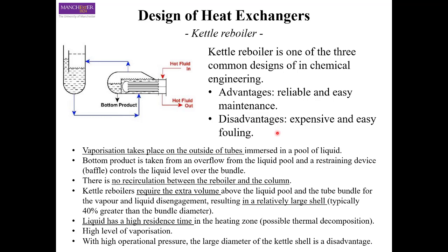On the other hand, they are very expensive and easy to foul. Sorry. The reason they are quite easy to foul is because just like your kettle, for example, you normally see that there is a lot of limescale on the kettle heating element. So similarly here, because it is heating an impure product, very often you have limescale or some sort of fouling on the tube surface that reduces the heat transfer.